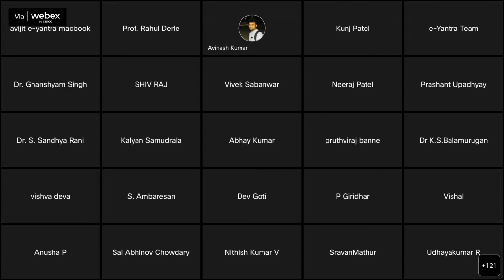a widget, e-Yantra iPad, to your screen, and you can see that we have one self-balancing robot here. Whatever we have been talking about is implemented in this system. We have motors with some gearbox here, then a battery and motor drivers. Motors cannot be directly driven using the microcontroller because they draw too much current, so for that we have motor drivers.